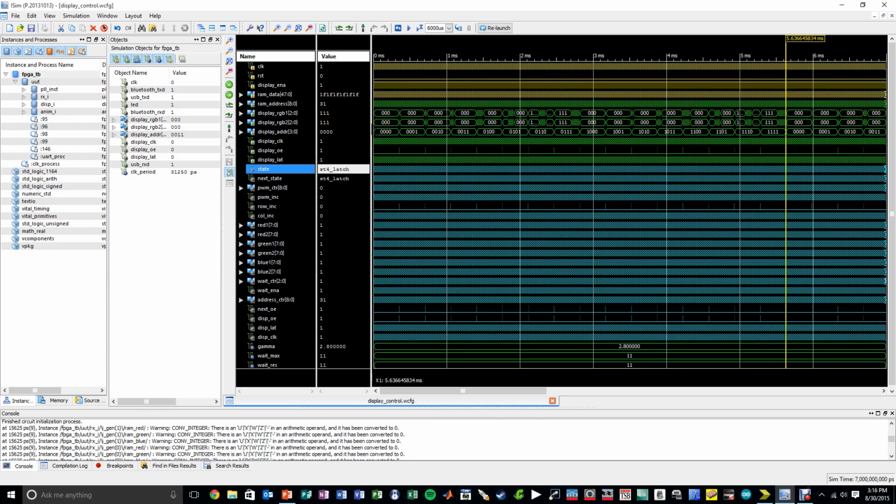Yeah, so the way we achieve 8 bits per color, or 24 bits RGB, is that we turn the LEDs on only for a portion of the time, because the LED can either be on or off. There is no dimming function. So the way to dim the LEDs is to not have them on all the time, but to only have them on a portion of the time. The granularity is 256. So we can have them on 1/256 or 2/256 of the time duration that we drive one line, and that way we can achieve 256 different brightness levels per LED, and that gives us 8 bits of resolution in the brightness. And as we have 3 different colors, it's 24 bits total.